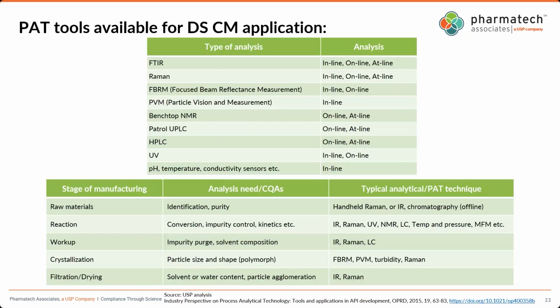As soon as there is a disturbance in any one of the pumps or any one of the in-process parameters, you could see a spike going up and down. That could also give you an understanding of whether your process is in control or not, and that could decide whether to collect or divert. So it has wide applications depending on your processes. You can choose whether to use it as an endpoint or to control your process.